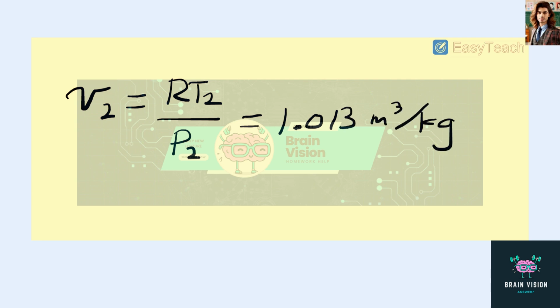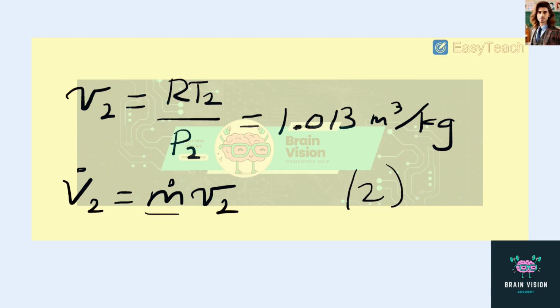We can use the specific volume to easily solve for the volume flow rate by saying that the volume flow rate at the exit is equal to m dot times v2. As you can see, this expression is dependent on m dot, which is dependent on the exit velocity. Therefore, this plot will also show some kind of relationship between exit velocity and volume flow rate, which will be the second graph that I show.